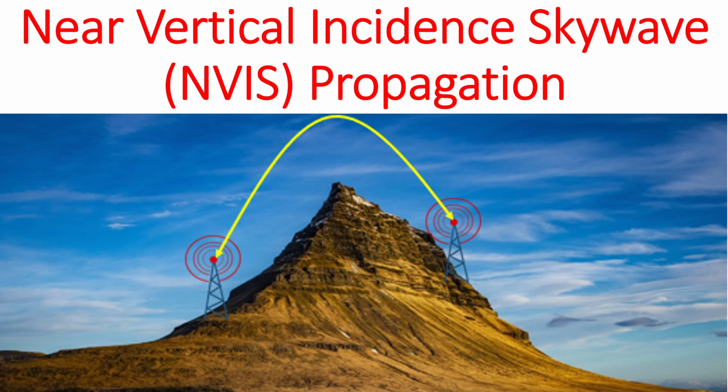At lower angles of radiation, the radio waves travel more distance through the lower layers of the ionosphere, increasing absorption and reducing the chance of refraction from the F layer with good signal strength. Frequencies in the range of 2 to 8 MHz are suitable for bouncing off the F2 layer of the ionosphere. This would make communication better on 80 meter at night and 40 meter during daytime.